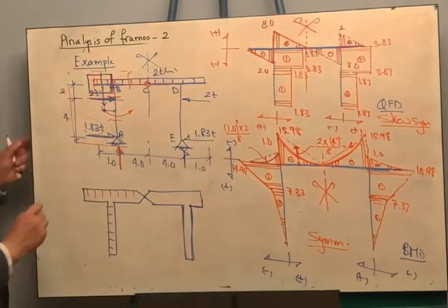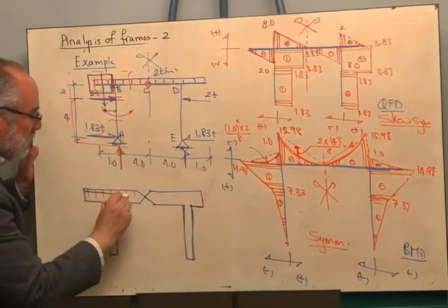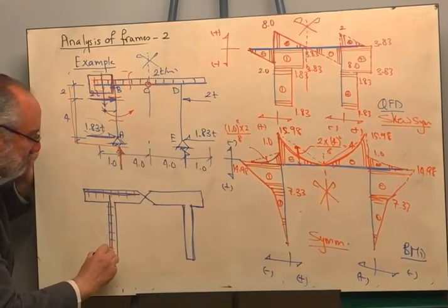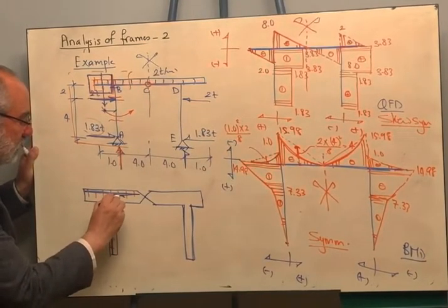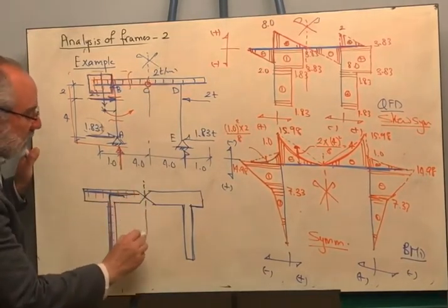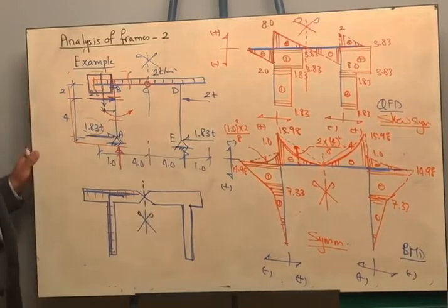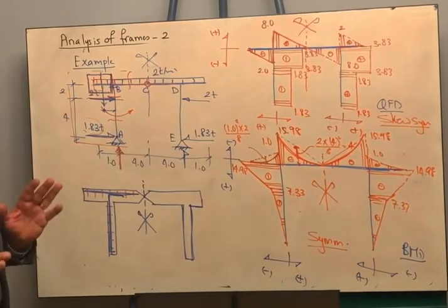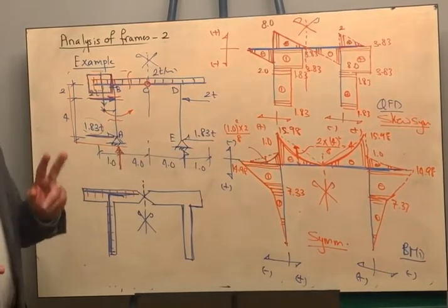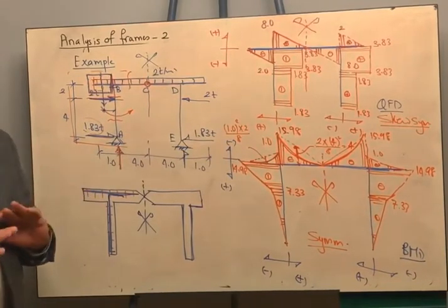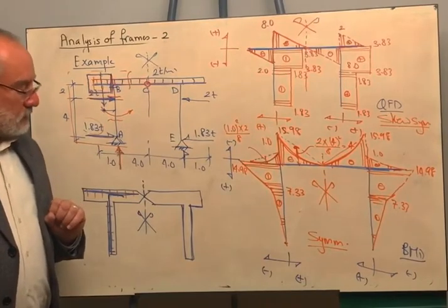So when I'm putting the steel reinforcement, the steel reinforcement will be located at the upper fibers, and the steel reinforcement will be located left of the column, like that. And of course this is symmetric as long as the bending moment is symmetric. Okay? So we solved so far up till this moment 4 problems of frames, 2 problems on each lecture. Your exams and your assignments will not be more difficult than this.